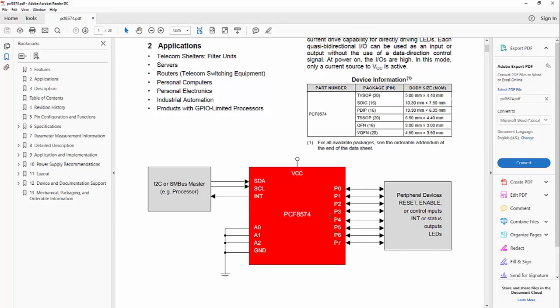We need it because, for example, if you have a few chips connected to the same line, because I2C can control up to 127 chips or units, we want each one to know when we are activating the chip. All the chips will be listening, and just the one that is in the same address will react according to the data that we send.